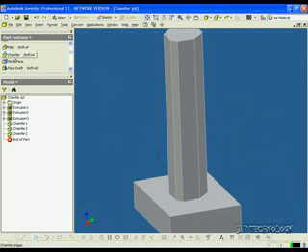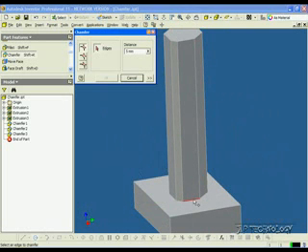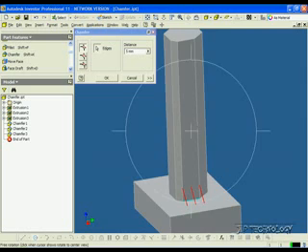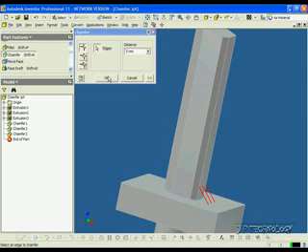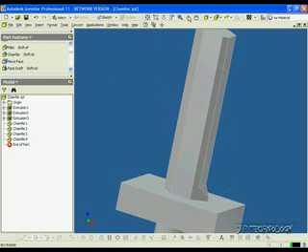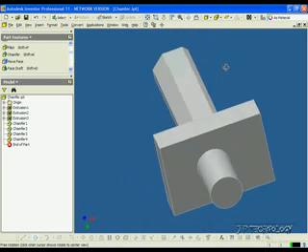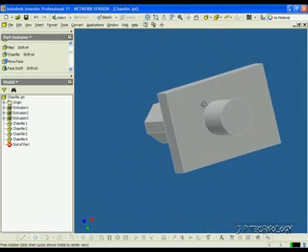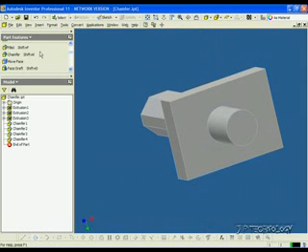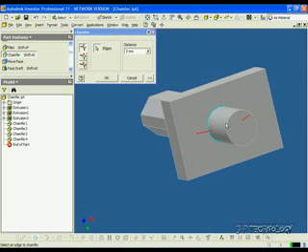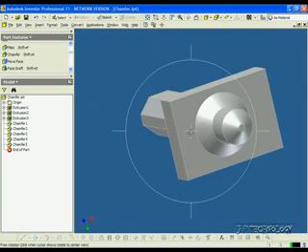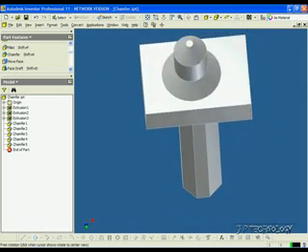Okay, now let's click chamfer again, and we're able to do bases. So if we click this edge here, it actually adds to the material. If we look on the side, click OK, and now we've chamfered onto the side there. Now we're also able to chamfer circular edges, so let's click chamfer, let's click this edge here and this edge here, click OK, and we've chamfered 5 millimeters on the bottom and the top.